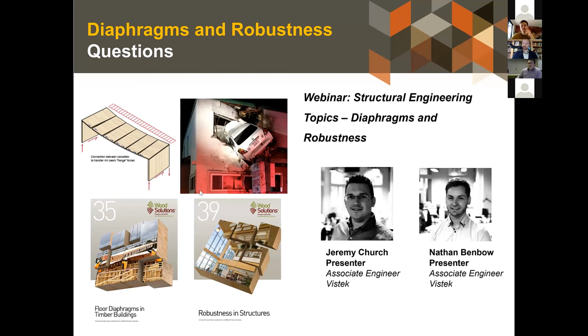So you, Jeremy? Yeah, so if you're sourcing it locally, so we use a combination of, if you're using local CLT, there's a large CLT manufacturer in Australia, and if we're using their product, then we will use some partial factors from the Australian standards, as well as all the loading criteria from the Australian standards, and all the material factors for timber design, and appropriate it to that.